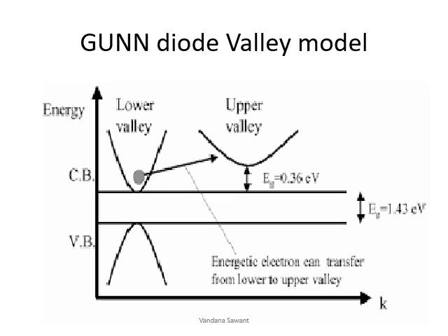Now, how does this device work, or how is the current output in this device? Generally all the substrates have two energy bands, the valence band and the conduction band. In this device, as we have many layers of N-type, N plus type material, in the conduction band there are many energy levels. These energy levels we can call the lower valleys and the upper valleys.